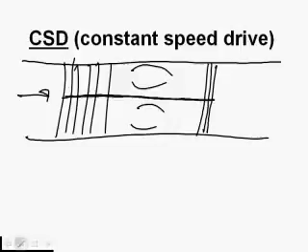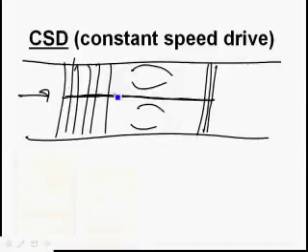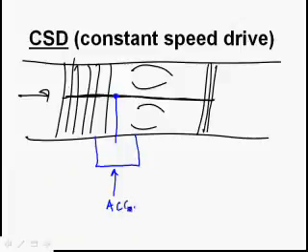What we can do is take power off of it on another shaft, and we can call this box here with a lot of gears in it the accessory section. I love accessory because it has 2 C's and 2 S's. This accessory section, it's just like the back of a Cessna 172 engine where you bolt the magnetos and you run the vacuum pump, or on a car where you run the fan belt to run the alternator and run the air conditioner.